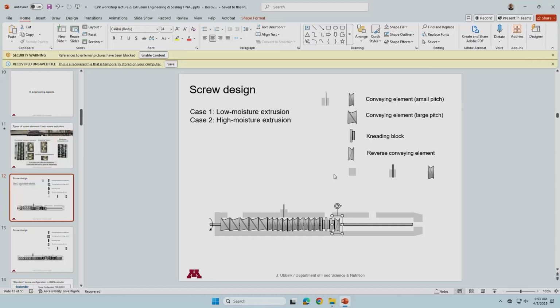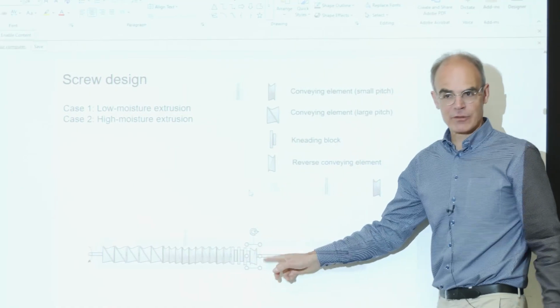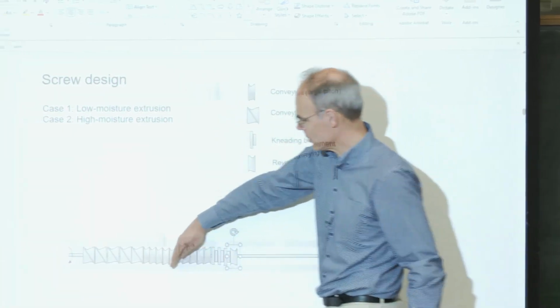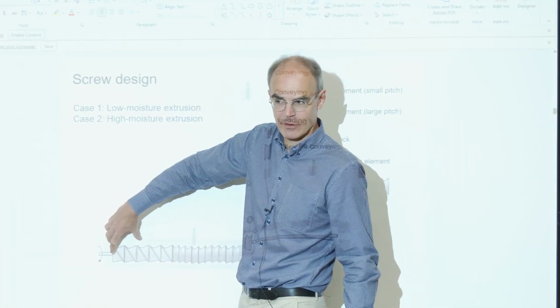So the material starts to be transported here, hydrated, heated up. Then in that zone, there is back pressure. So it really helps to fill that kneading zone. You don't want to have too much back pressure because you can't transport it anymore. Because it will really stay there, and suddenly you have blocked your extruder.